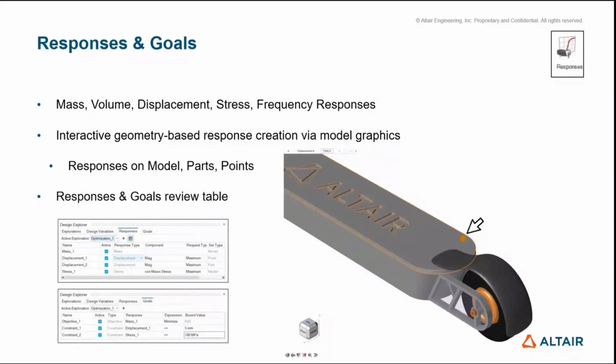Responses, similar to HyperWorks, are very graphics driven. We can support mass, volume, displacement, stress. New for 2022.1 is a frequency response as well. I'll demonstrate that. And it's all, again, very interactive, geometry based. You just click on your model. I want to have the displacement here or the stress of this part, and so on.